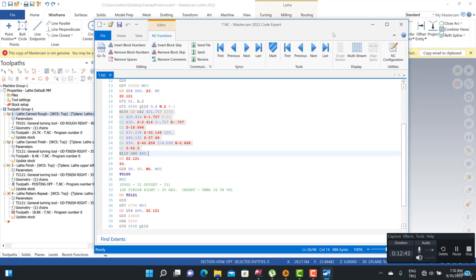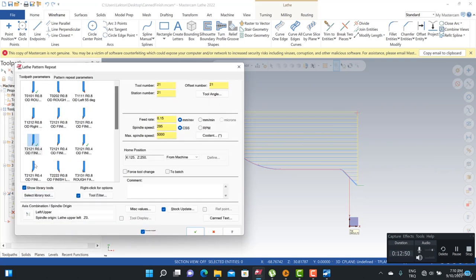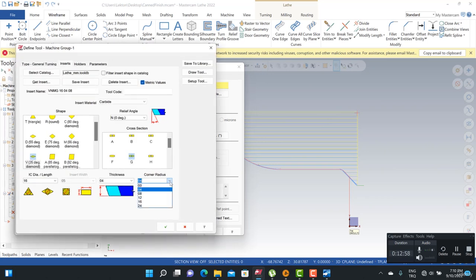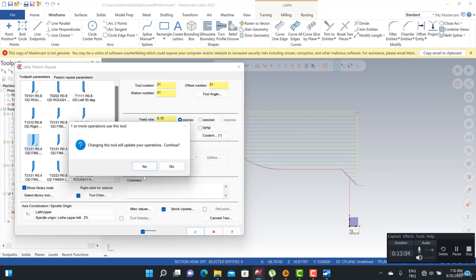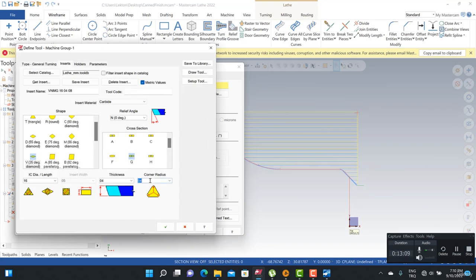Okay, so when I turn here, we can also use a different tool radius. I can double click on it, and then we can use 0.2 tool radius here. Okay, let me change that to 0.2.